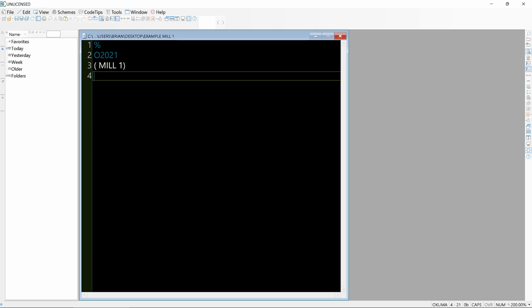If you use the workbook or even the CAM instructor product, they have strict or predetermined tool lists. You could do that too. But for our setup on these first 2 examples, we'll just keep it simple, tool 1 and tool 2, because I want you to practice also clearing offsets when you're done. So we can call tool 1. T1 M6, and what I find is that over here in parentheses, it's not a bad idea to put load tool 1, and this puts it in English, which is helpful.